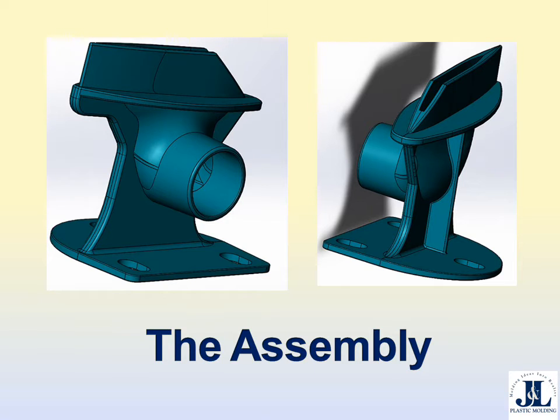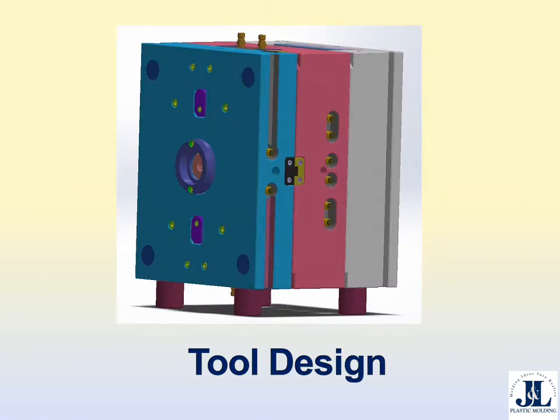J&L was awarded the project and issued a purchase order, and we began the tooling process. Upfront communication in the design phase with our vendor and our final design approval is crucial to an overseas tooling project. Before any tool steel was cut in the nozzle assembly project, our tooling vendor in China submitted a 3D CAD tool design to J&L. This allowed J&L to see the detailed design, provide feedback, and issue final design approval.